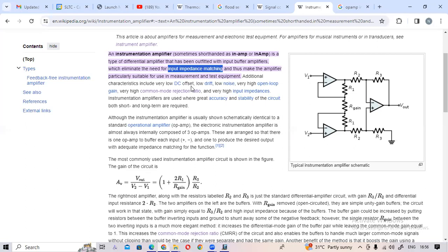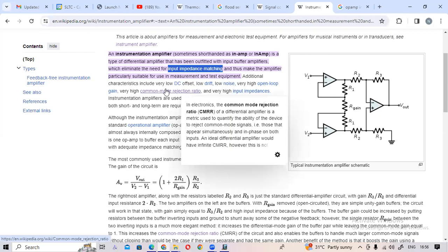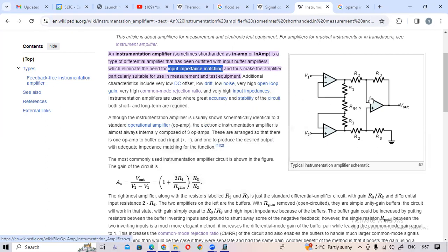When you are doing a project, especially telecom students, who will do some projects related to communication for their final year, when you are designing an amplifier or filter, that kind of thing, you always think about the input impedance. You have to design the circuit for the relevant input impedance. That is very important, otherwise your circuit will not work.